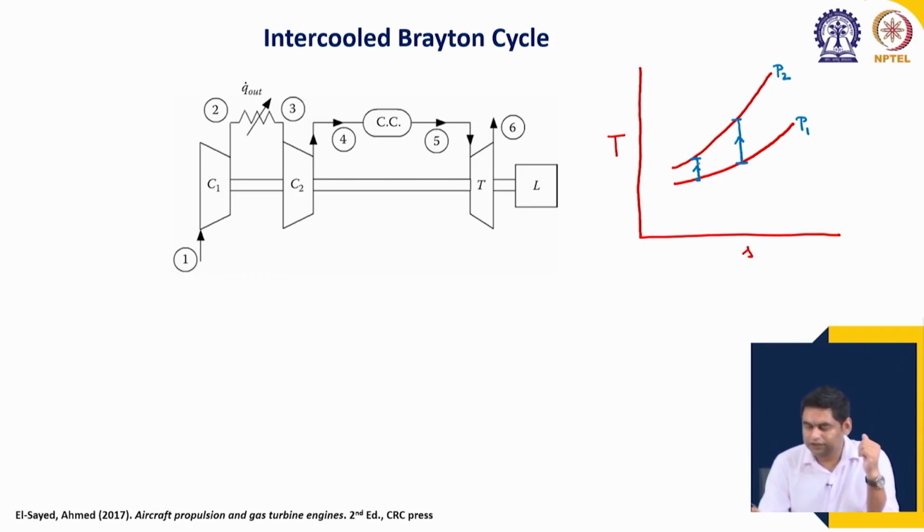Anyway, we see that if we can somehow lower the temperature at which the compressor, or part of the compressor, operates, it will be possible to decrease the amount of work required to run the compressor. So, the intercooled cycle has been developed keeping this concept in consideration.